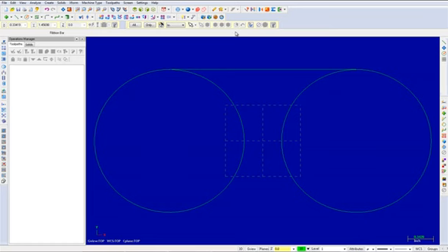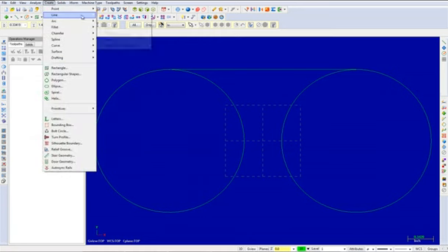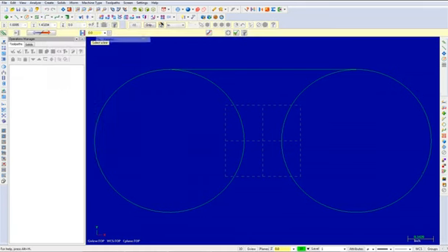The next thing that we will do is create a line parallel. Select Create, Line, Parallel. Select the following line as shown, and then pick a point below this line. In the ribbon bar, change the distance to a value of 1.7. Press Enter. Your line will be moved. You can now select the OK button to exit this command.